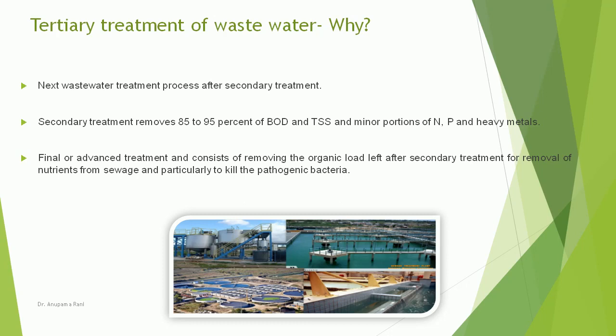The purpose of tertiary treatment is to provide a final treatment stage to raise the effluent quality before it is discharged to the receiving environment such as sea, river, lake, ground, etc., or to raise the treated water quality to such a level to make it suitable for intended use. This step removes different types of pollutants such as organic matter, SS, nutrients, pathogens, and heavy metals that secondary treatment is not able to remove. Wastewater effluent becomes even cleaner in this treatment process through the use of stronger and more advanced treatment systems.